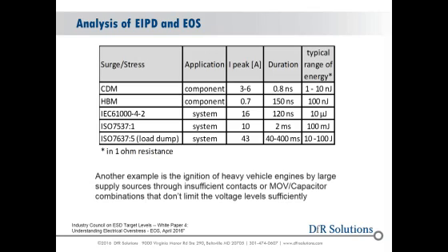We've also seen situations, for example, where the ignition of a heavy vehicle or truck can trigger a possible damaging effect to MOVs or capacitor combinations on that input that don't limit the voltage level sufficiently.